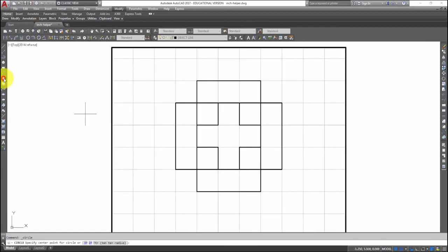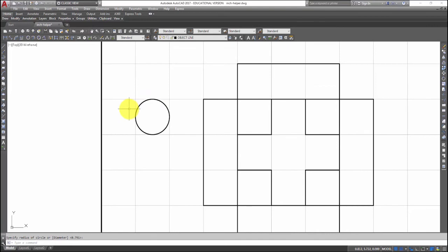It can also work for circles. So let's just say I have a circle here. Let me hit escape. If something's going on with your mouse, just hit escape, and that usually clears things. Okay, I'm going to draw a circle right here. Now, what are the steps to do an offset? O, enter, type in the distance you want to go. Let's say I want to go 0.5. Enter, click on the line, then click in the direction you want to go, and then you just offset it.